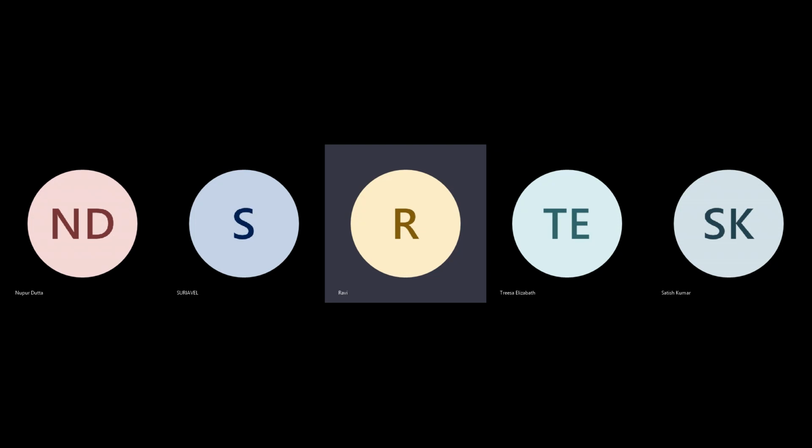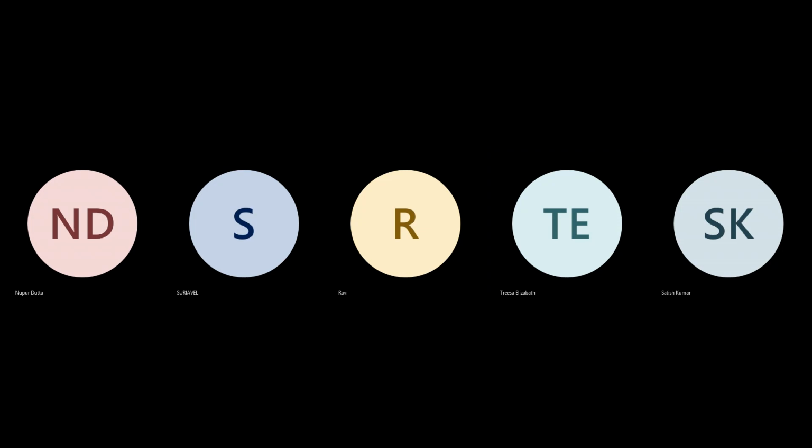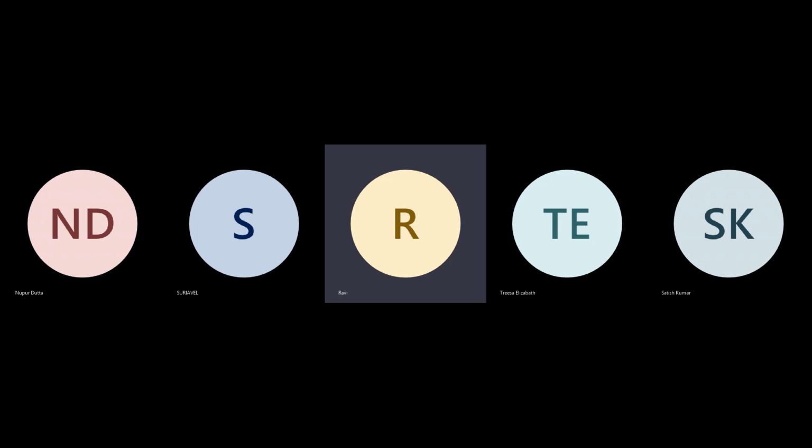In a floor plan, as I said, when you are doing placement, you have to ensure that if you have to do special cell insertion, etc., you have created the necessary setup and they get priority. In a flow, before doing placement, you have to make sure all the specific constraints are set: path grouping, critical paths, critical range, nets, everything, one after the other.